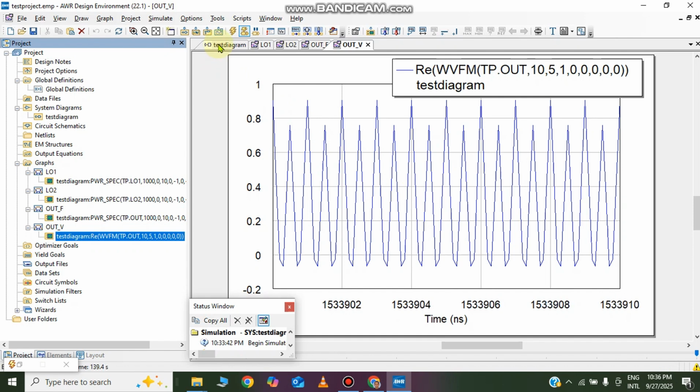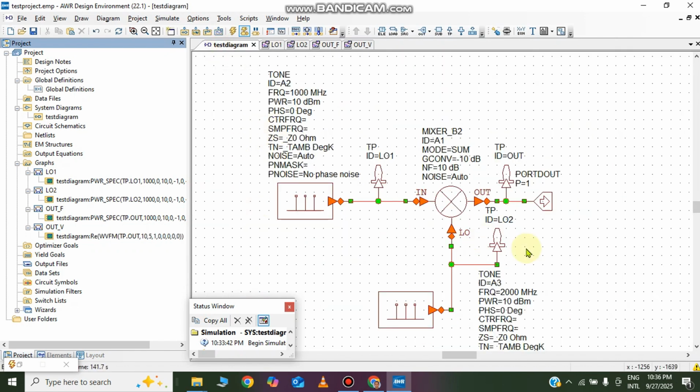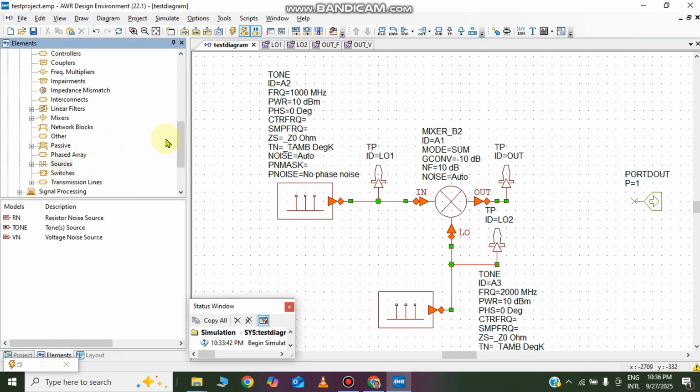To go back to our diagram, now I would like to add a filter into this circuit. For that, I first stop the simulation by clicking, I can pause the simulation. Then I will click in here and press delete to get rid of the wire. I will drag this element out, then go to the elements tab. Then I will look for filters.